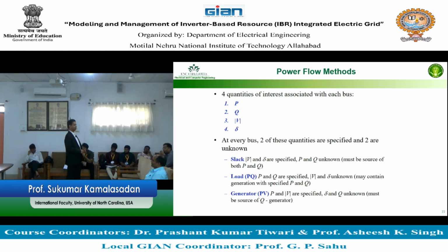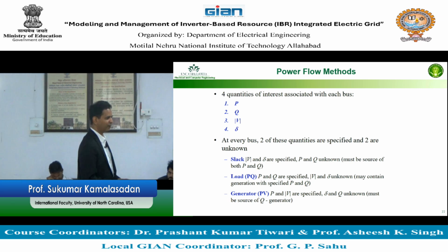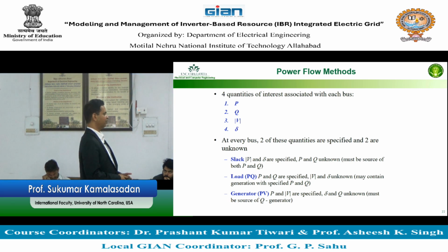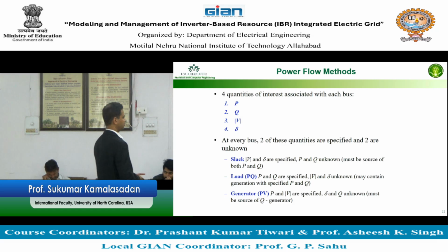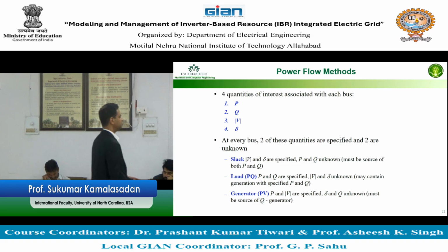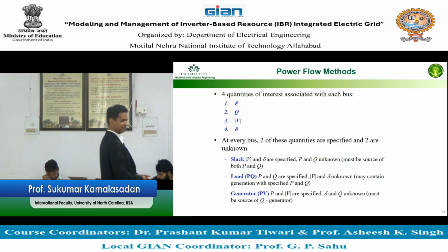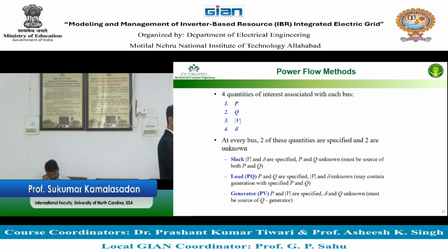Now we also have a problem. What is the problem? This is great, but who will take care of the losses on the electric network? How do you know the loss power? If you know the power for the losses, I can take the number and add it to this math and I'm done, right? Who will take care of the power for the losses? You don't know that, right? So the power for the losses means what? P and Q. There are two losses, right? So there is a loss term that needs to be accounted for.